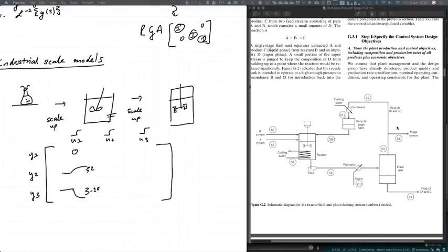And so in control terms, what that means is that I have a limited number of degrees of freedom. So I'm trying to maximize product, but I also don't want to blow anybody up, and I want to keep the reactor running, and I want to make sure that the levels just don't overflow. And there's a whole lot of safety requirements. And I have to do all of those things using only a handful of different valves that I can place around the system.